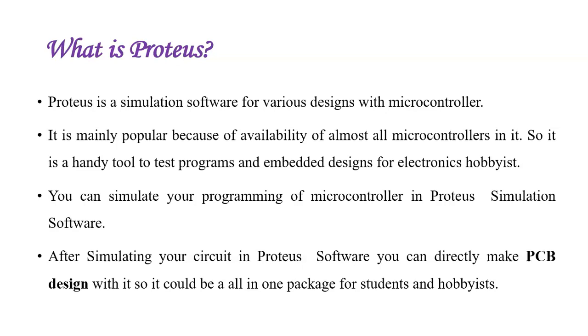So with the help of this simulation software, you can design your circuit, you can program and load your code on the microcontrollers, and finally you can simulate to test whether your circuit is working or not before you go for the implementation. So the main purpose of Proteus simulation software is to develop PCB, which stands for printed circuit board. But you can easily simulate the circuit before you go for PCB design.